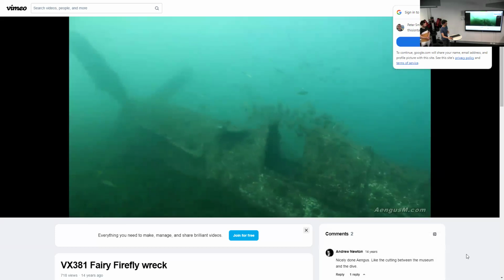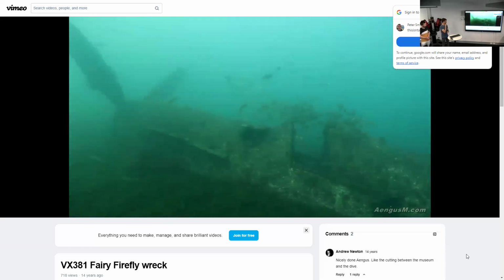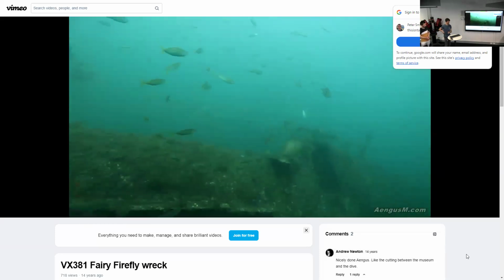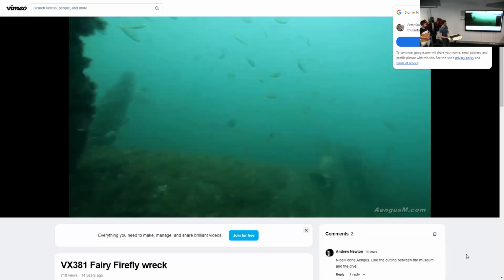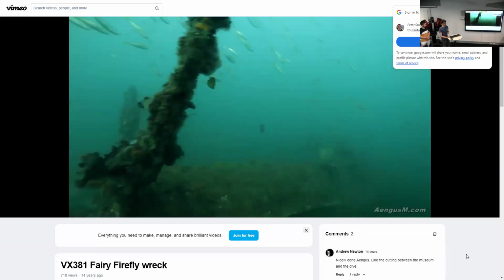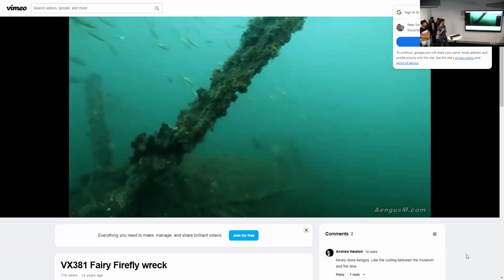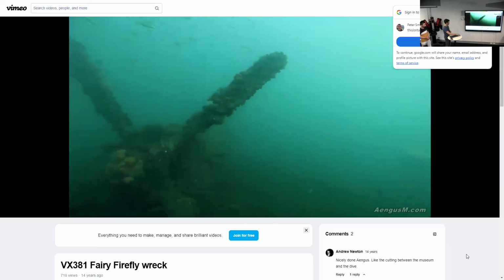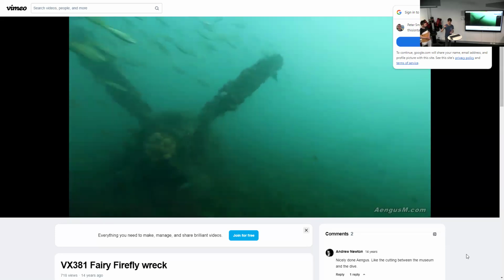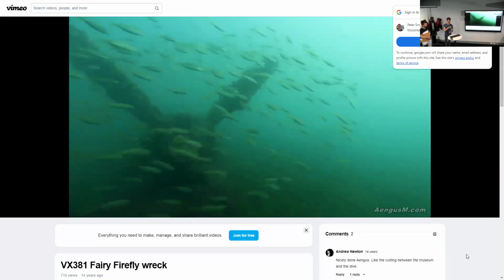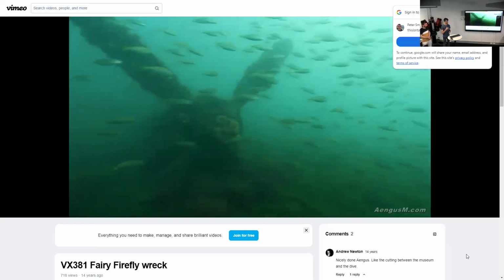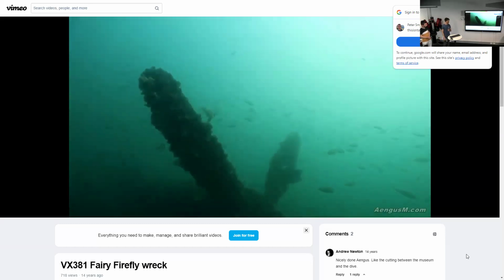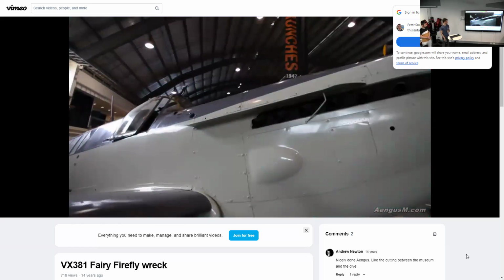So there was some doubt, given that it's 14 meters down, as to whether or not we would be able to sense this from the surface. And so obviously, given that we had a simulator which is capable of simulating these kinds of environments and telling us whether or not a sensing suite will be adequate for a given situation, we simulated it. So we created a rough model of this plane. We chucked it at 14 meters depth. We mounted a single beam sonar to a SurfBee in our simulator, and we drove over,